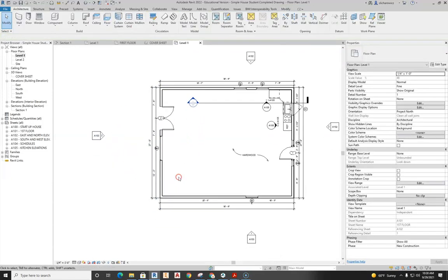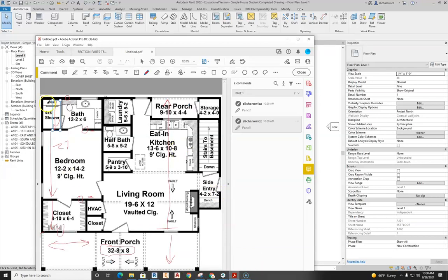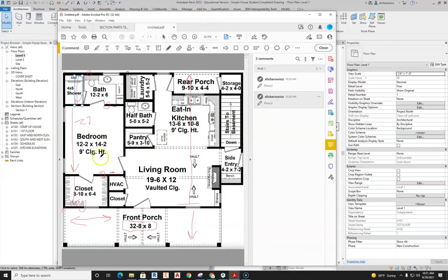Now, the next thing is let's start thinking about adding some interior walls because we kind of have a rough shape here. So I jump back out here and say we got some interior walls down here. Probably like to start down here in the corner. I want to avoid this at this point because I'll end up working this a little bit when I kind of work up and around the drawing. All right. But let's start thinking about these interior walls here. All right. So our interior walls, this is going to become a 2x4 wall. 2x4, 2x4, all 2x4s. No other layers necessary.